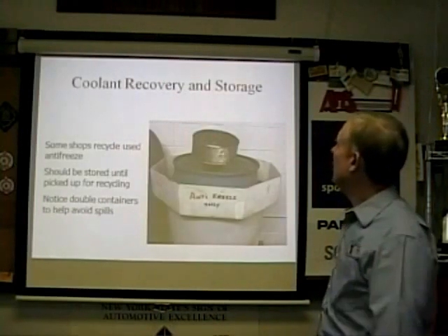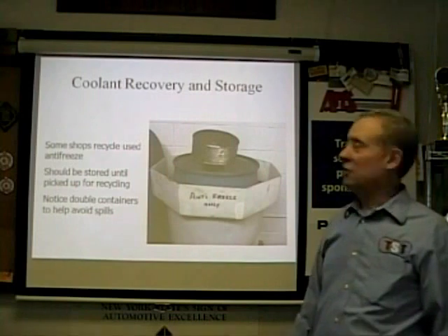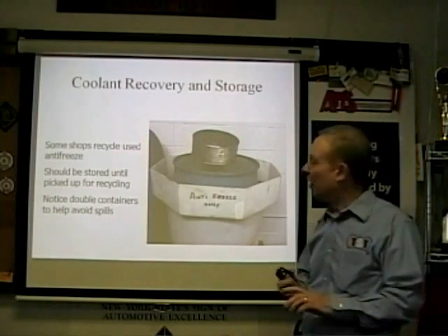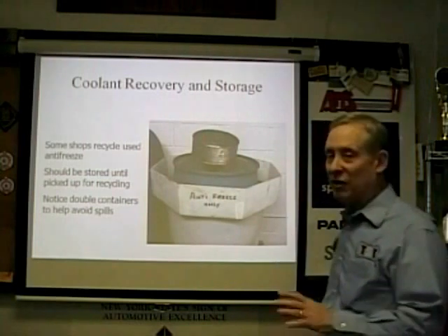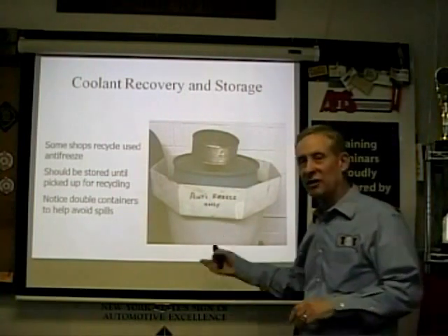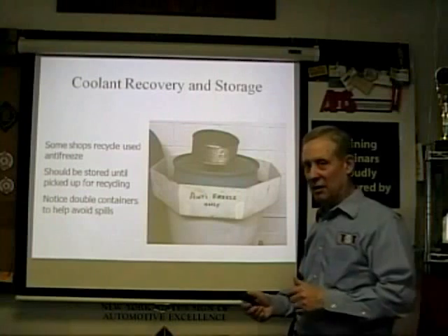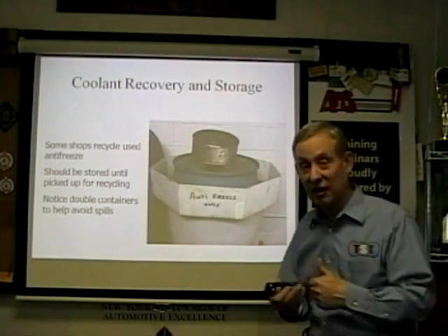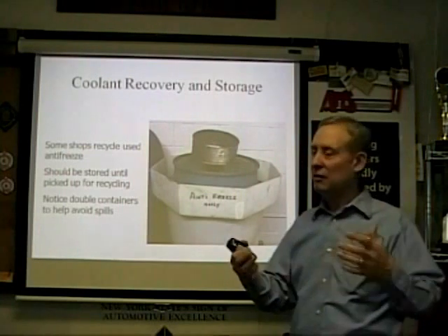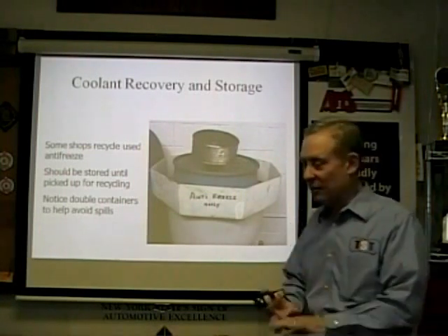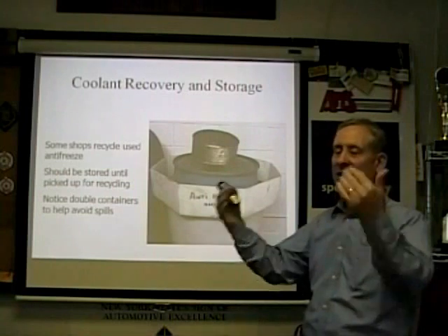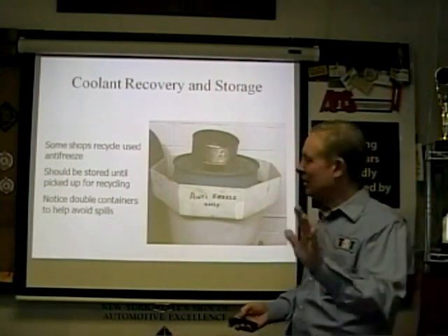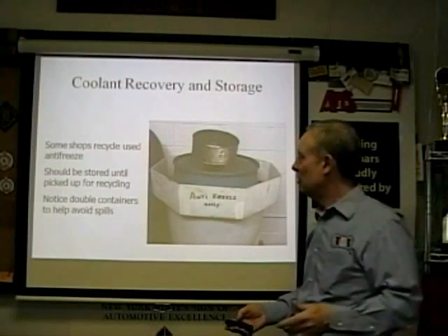All right. Coolant recovery and storage. Some shops reuse antifreeze. I've already said it. I don't like it. The only thing I ever liked to do with antifreeze was put it in the drum so it could be sent for recycling. If a manufacturer reuses the ethylene glycol, I trust their engineers and their chemistry to make it a good base product first and add their additive package. But once you're doing it in your own shop, it's very hard to have quality control. And they'll have a warranty on it.